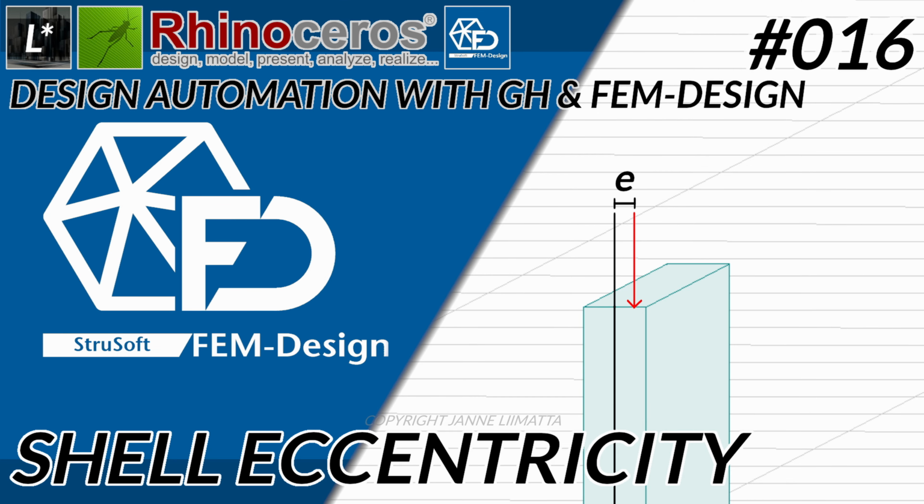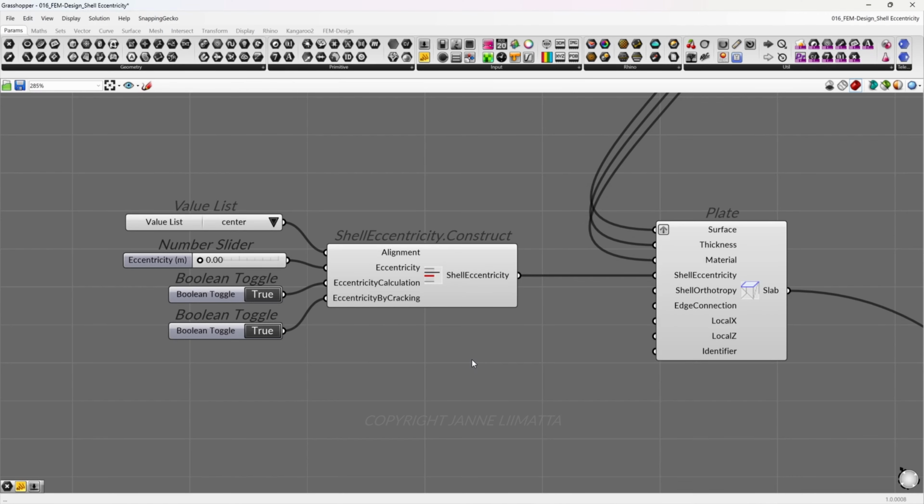When, for example, analyzing walls that have slabs connecting to them from only one side, eccentricity needs to be taken into account because it will increase the bending moment in the wall. You can edit the alignment and eccentricity of a plate by using the Shell Eccentricity.construct component. Connect it to the Shell Eccentricity input of the plate or wall component.